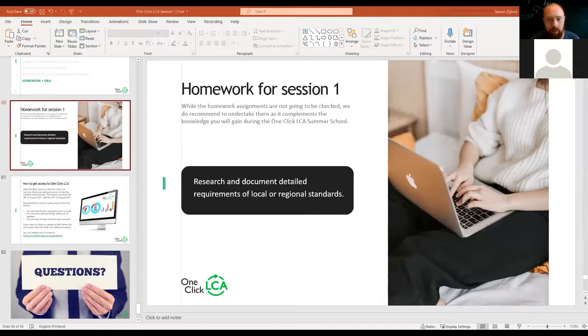Yasid asked if we can tell about what the structure, arch, and building services embodied carbon percentages. Quite tricky. Structure is usually the biggest. Finishes can also be quite big, but it's never as big as the building services. I would say if you're joining on Wednesday and you're using Carbon Designer, you can see it yourself quite easily. Building services can be a very large part of the emissions. It can be up to 40 or 50%, but usually building services are left out of assessments.